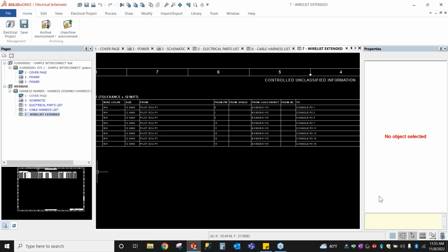The big question is importing parts. I got a lot of questions about importing the information that they might already have, whether it's in a spreadsheet or they have the data on the graphic representation of their symbols and stuff. What are the best ways to go about that? My favorite way, if I already have existing BOMs or an Excel spreadsheet of a bunch of usually manufacturer information, one of my favorite things is on the import export tab, there's an import data button.